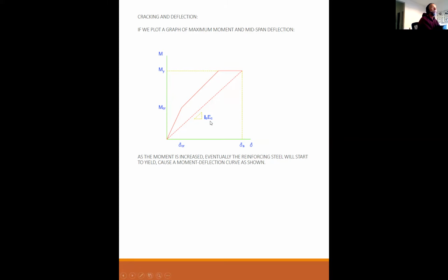And so I sub e really starts to flatten out, and your deflections will get very, very large with the same applied moment. The final stage is for illustration only. No valid design will allow beams to yield under service loads. Yeah, it's just kind of obvious. You don't want beams yielding and cracking and sagging under your design loads.